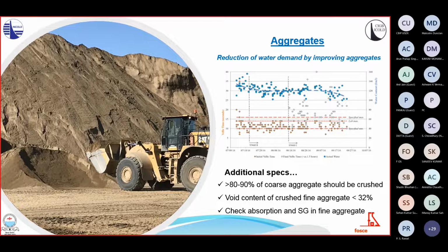And the development of the water content of the mix is shown above in blue on the right axis, as can be appreciated from early values up to 140 liters per cubic meter of free water content in the mixes. The optimization of the aggregates has reduced this value down to almost 105 liters per cubic meter in the last mixes. This 35 liters less water per cubic meter for the same consistency provides a large margin for the reduction of the content of cement and fly ash in the mix, aiming to achieve a certain level of strength.